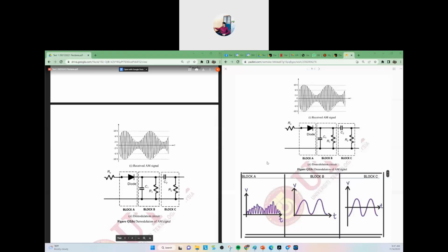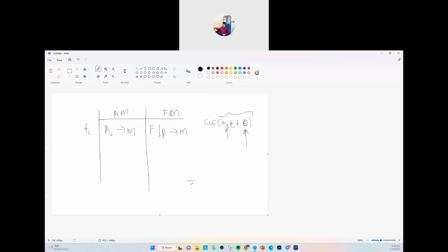So this one is actually your modulated signal, but rectified. So we only take the positive half. But if it's reverse bias, no problem, then we take the lower part. But you need to understand the concept. So this is correct, and this will involve the tau. Tau equals the RC value, the one with the rectifier.